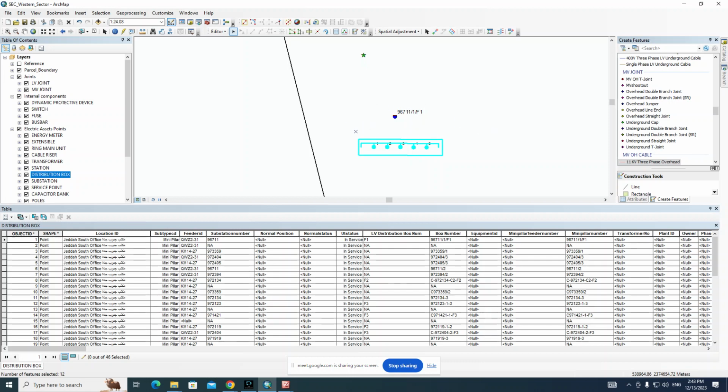This will be the center. Put it on any edge or corner. Then I will place this corner here, so I can snap it. Now I will click on the Rotate tool.